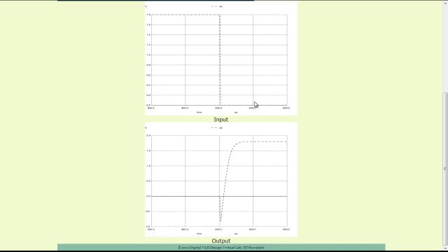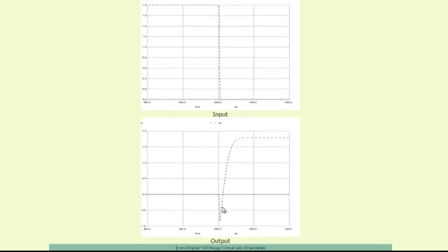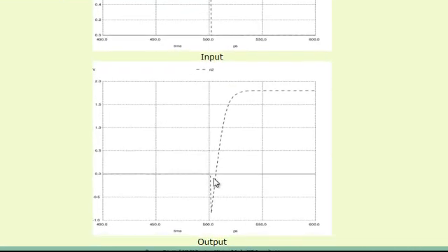Notice the input and the output characteristic curve is now plotted between 400 picoseconds to 600 picoseconds as we required. This will help us to measure the time more clearly for the output of the inverter to rise from low state to the high state. Thus, we can evaluate the rise time of the inverter.